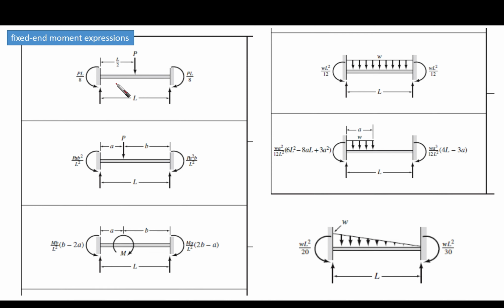So what is the meaning of fixed end moments? Fixed end moments is whenever we have a beam, continuous beams, for example. Whenever we study one section, if we say this is A and this is B, a section of the beam, then we are going to assume it to be fixed from both ends as long as this is continuous above the support, there is no link or intermediate hinge, then this end is going to be fixed and this end is going to be fixed.